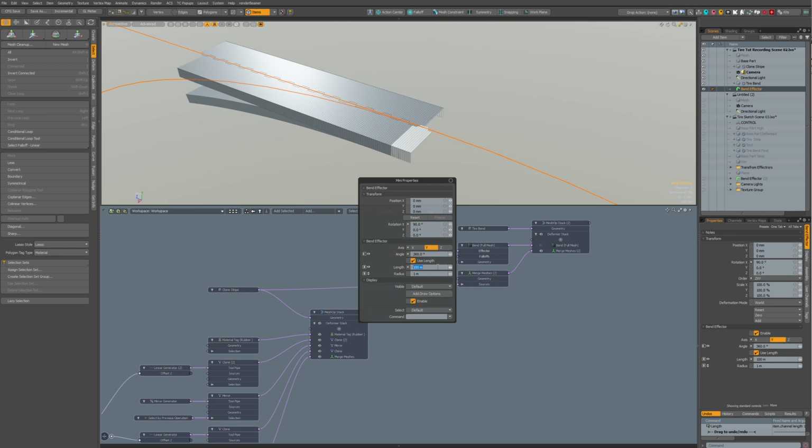So there's a setting in this new version that if I put 25 here, it's 25 meters. If I put 1, it's 1. If I put 0, then it goes to millimeters. Before, it always used your default units, so you had millimeters by default and it always wrote millimeters.